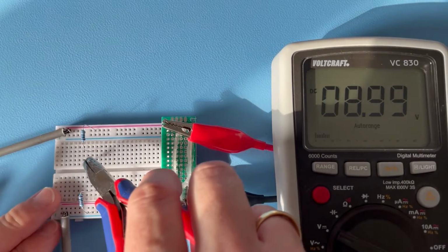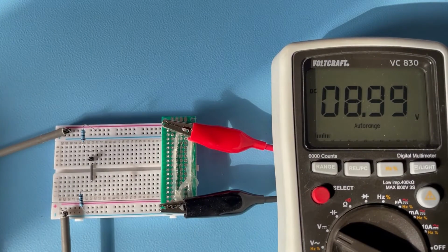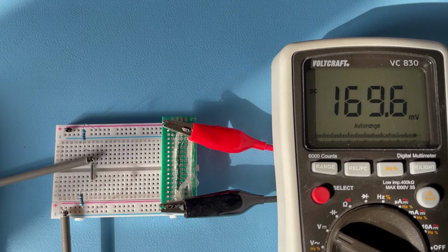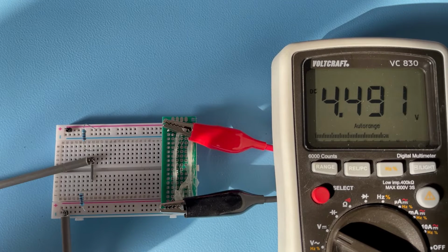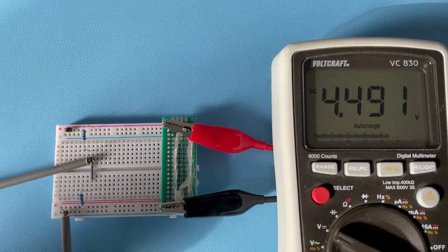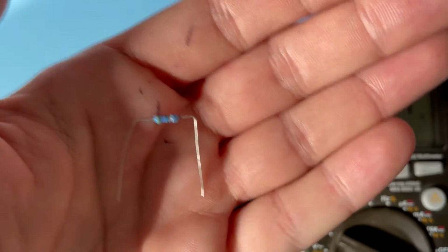There's a little measurement pin in here, and I take the measurement from the 9 volt and I put it here, and you see, not perfect, but quite 4.49 something, so very close to 4.5, so very close to the half. Reality is not always as perfect as theory. But now we do the interesting thing. That is a 47 ohm resistor, so very close to 50 ohm.